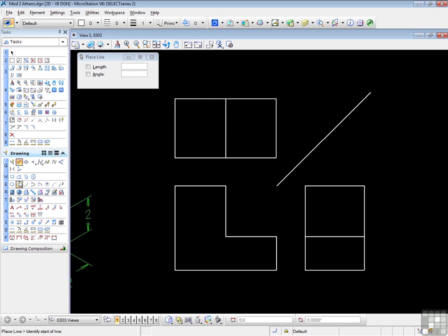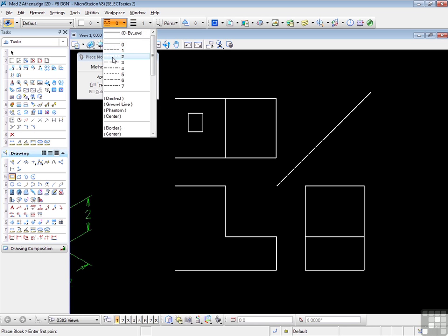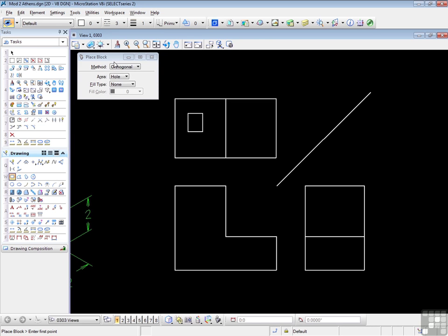Now let's add another feature to this. Let me add a rectangle to the top view in that face, which is a hole going right through the object. So it's quite simple now to add the hidden lines for that. And I'm going to use line style 3. This is for convenience. You would normally use a custom line for this.